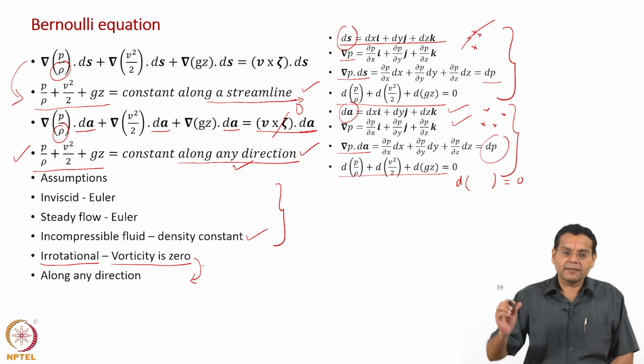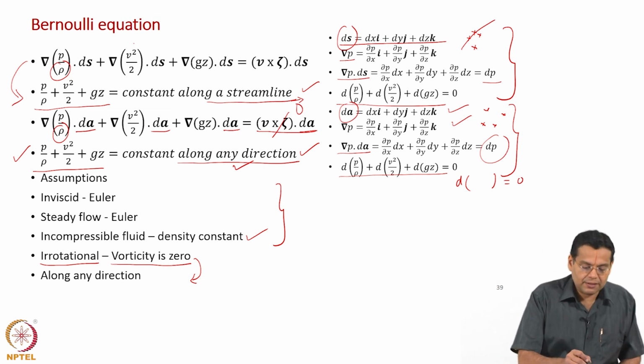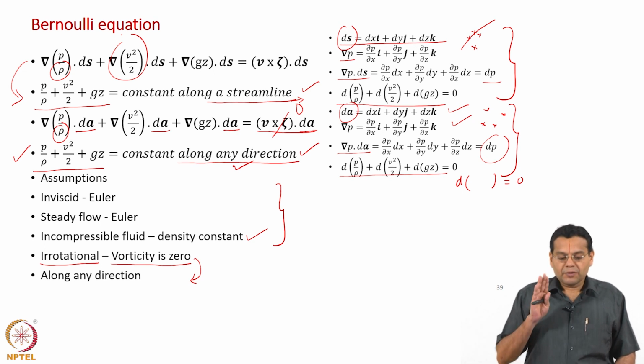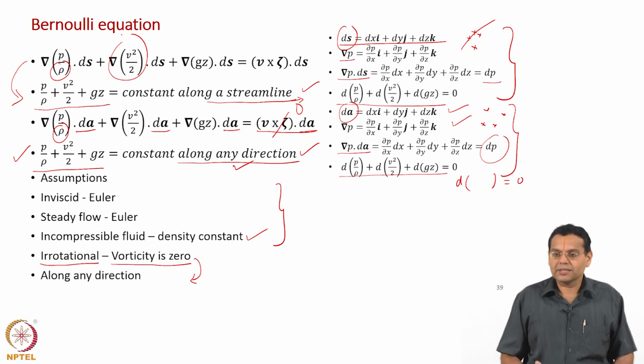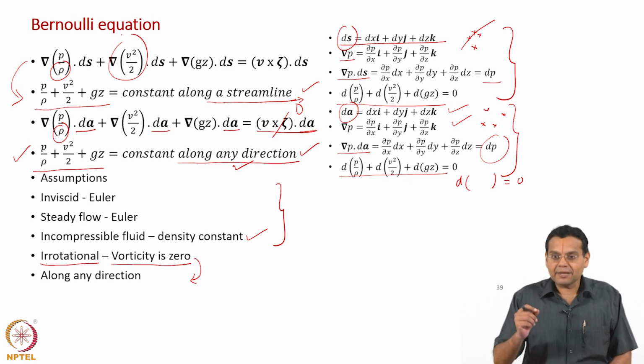They take a streamline, consider a movement of a particle along a streamline, they consider acceleration, which is our this term, okay, and then for the forces they consider only pressure force and then gravity force, that is all they consider. They do not consider viscous forces. That is what we have also done. Though we started with Navier-Stokes, we wrote down the Euler equation neglecting the viscous stresses. Both have converged to the same physical significance, but the derivation is done in the beginning.